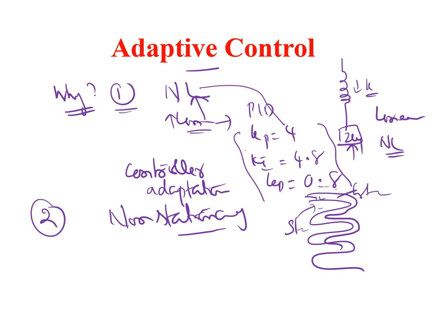After a few days, because the water is salty, when you keep on boiling, you will have some deposits. Because of the deposits, the heat transfer coefficient will be very poor.